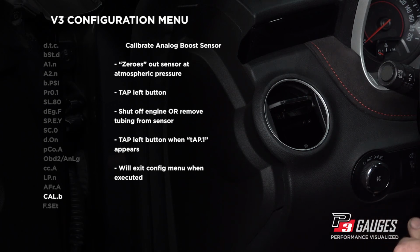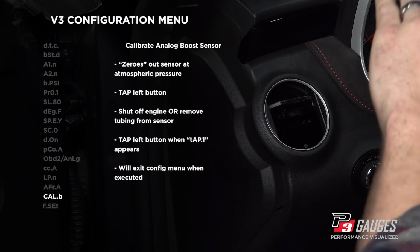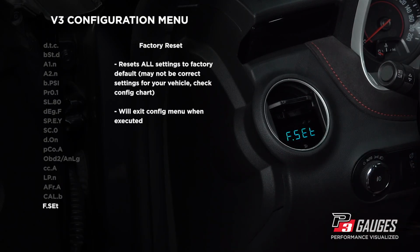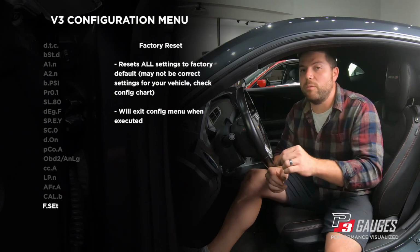Now your sensor is zeroed out so that when you start your car and make vacuum, your gauge is starting at the correct atmospheric 0 point to then go down and up based on boost and vacuum. So we can see our next setting is F.SET, and that stands for factory reset. This function is going to bring all these settings that we've gone over back to the default setting when we load software on the gauge.